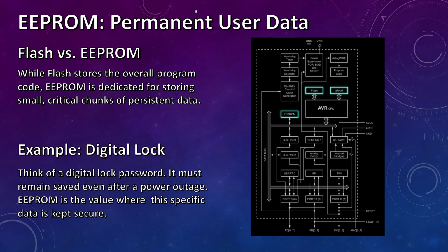Now let's come to EEPROM. Many beginners get confused between flash and EEPROM. The easiest way to remember it is, flash stores the program, EEPROM stores the important data.